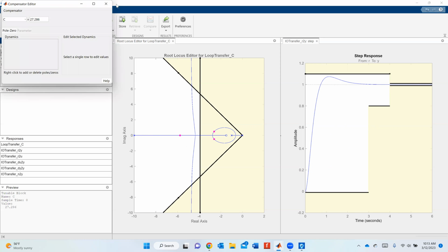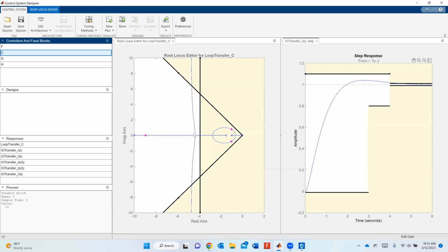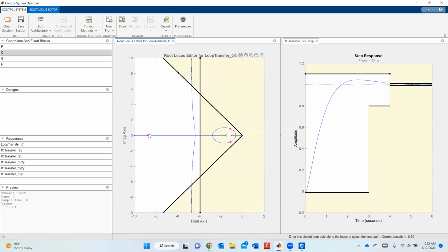And so looking specifically at our compensator here, which is basically your controller, your K. Here, when our K was equal to 27.286, we were fine. Notice when you have a gain of 10, though, you satisfy, oh, look, it's not exactly within there, so you need to go just a little more. And so when we get to about 15, that's a good value for a controller in order to get the desired response. So it falls within our limits.